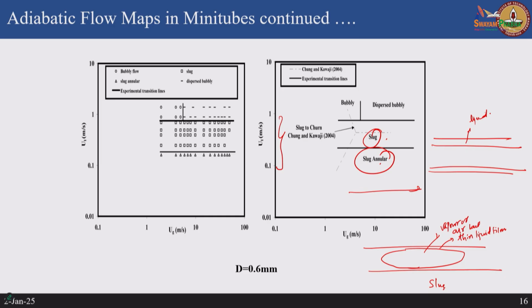Okay. Now, why this is efficient is this thin film is actually very efficient in reaching very high rates of evaporation, because when I have a convective flow, this liquid film is not going to be eliminated very easily. Although the vapor bubble is large enough, the evaporation is happening by means of a very thin film in the liquid region, and that is continuously fed by the velocity of the fluid. And the smaller the thickness of this film, the more rapid the evaporation rates will be.